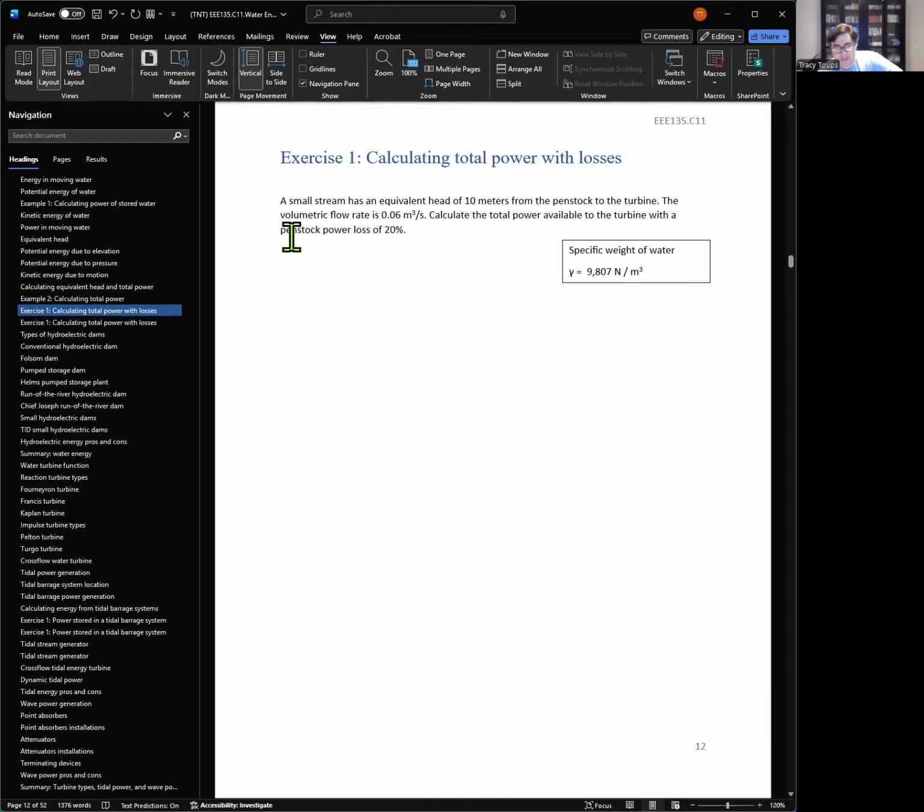What this part means is you will calculate your total power, and then you're going to lose 20% of that power as it flows through the pipe, because the pipe's not perfect. It might bend a little bit, so every time you bend, you lose some power. It might be crimped or something. Who knows? But pipes will always have losses. So whatever power you have, chop off 20% of that loss to go from ideal power to more realistic power, and that'll be your total answer.